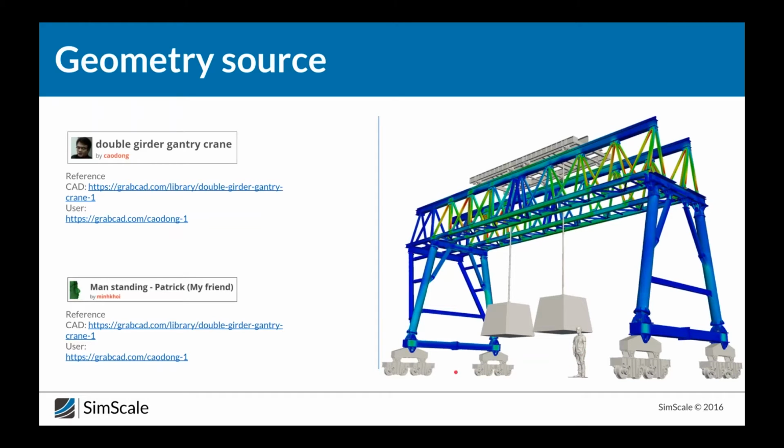The purpose of this is because this gantry crane runs on rails and the wheels have a flange on either side to locate them onto the rails. It means that the rails don't have to have a precise width, and so the width of the rails can vary without applying a large load to the structure. So this structure here is able to pivot to accommodate any change in width.